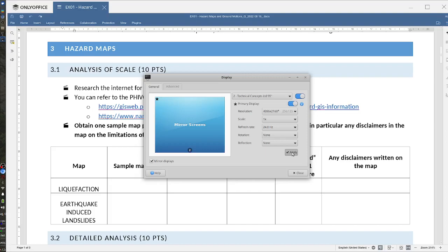So in the event of an earthquake or some ground subsidence, your mat will move as one. It can only tilt but it will not undergo differential settlement. Your house may just tilt, but that can be easily fixed. Okay. You just jack it. You jack your house.